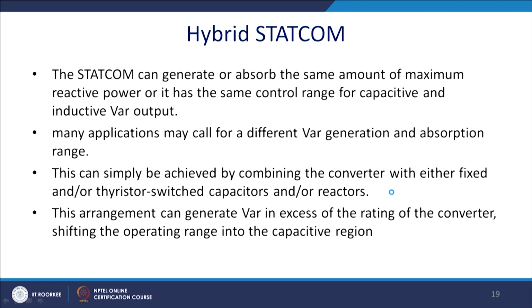So, let us now come to the important point. This is called hybrid Statcom. A Statcom can generate or absorb the same amount of maximum reactive power, or it has the same control range of capacitive and inductive output. So, it can work in either direction with the same power rating. Many applications may call for a different VAR generation and absorption range. That is one of the practical considerations we have to keep in mind while designing the Statcom.